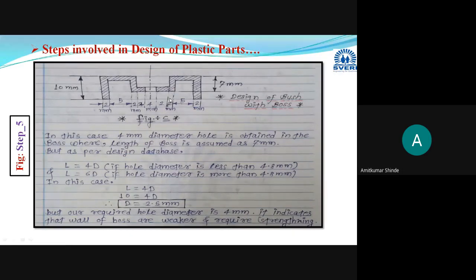Then what will happen while manufacturing this? You have to use the three plate mold. Already we have discussed two plate mold and three plate mold in the previous practical session, on the fundamentals of the injection molding process and the fundamentals of mold design used for injection molding. If two parting lines are there, we have to use the three plate mold, and in that the tooling will be very costly. It requires more cost.